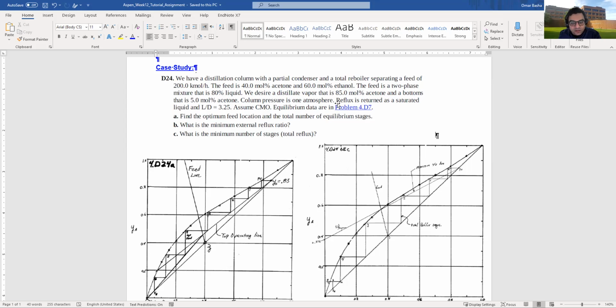So I'm going to drop my streams. I have my feed stream, I have my top, and I have my bottom streams right here. And let's just rename them. This will be feed. Let's rename them top and bottom. Oh, it doesn't like the name top, so let's call it vapor, and we'll call this guy liquid, or let's call it bottom. Okay. So I just put in my mass balance.